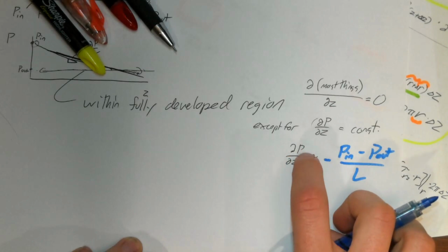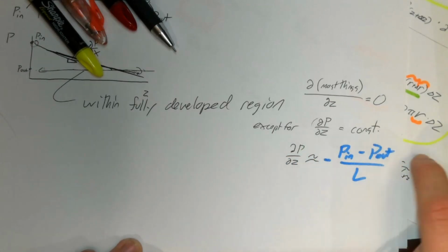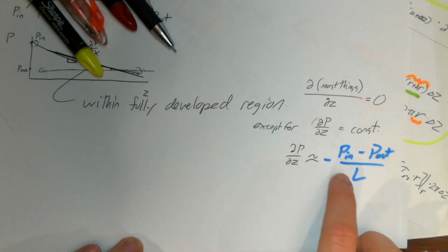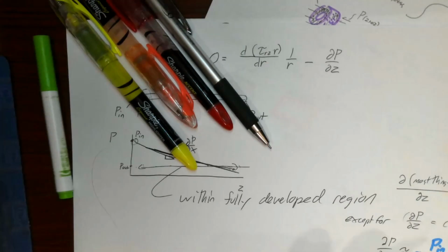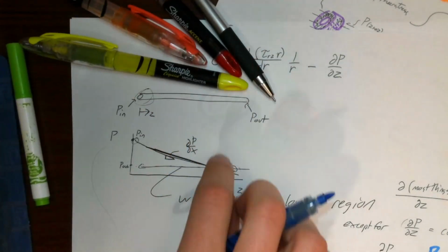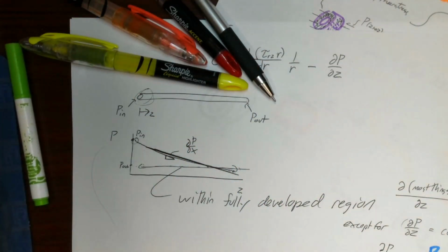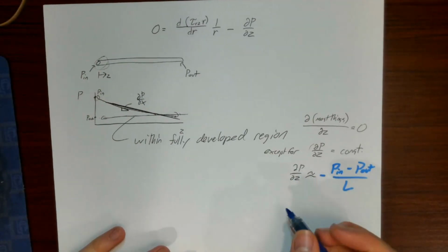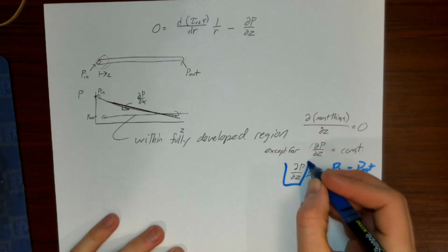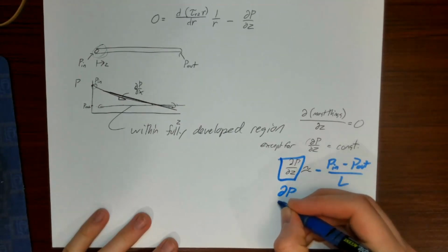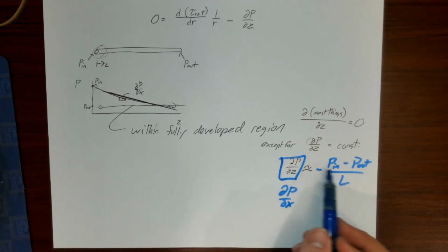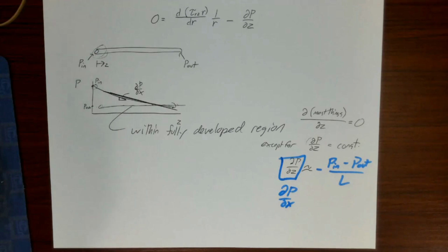And we can see that this dp dz has units of pressure per length, so pressure per length ends up working out here. And you could work this out from a y equals mx plus b type argument for what this line would look like. So what am I going to do? If I make this approximation, I'm now basically going to treat dp dx as a known constant, if I could approximate it in terms of these given constants.